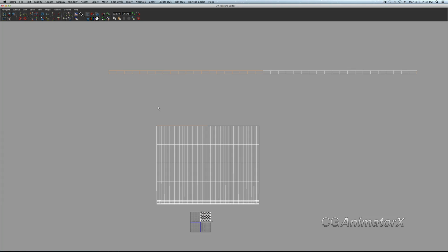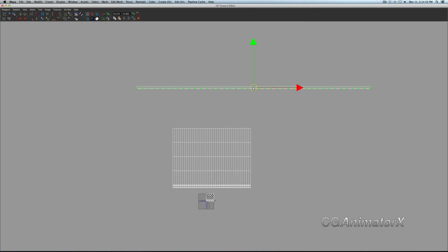One of the main things you have to take into consideration, in fact, I didn't do this myself, but I should, is that sometimes you have to make sure what section is being highlighted. Basically, what I'm saying is, if you select one section and it highlights this area, or it highlights this area, then you have to switch around the object, or you have to switch around the faces. So you have to flip them in essence.